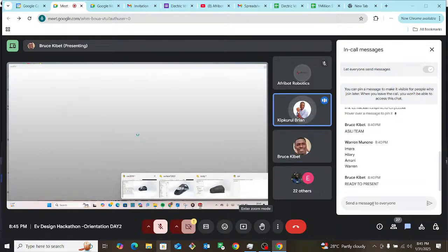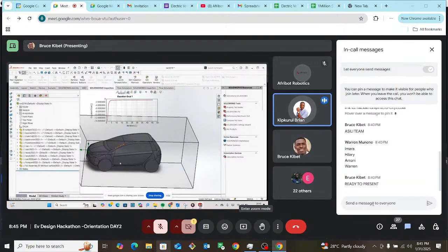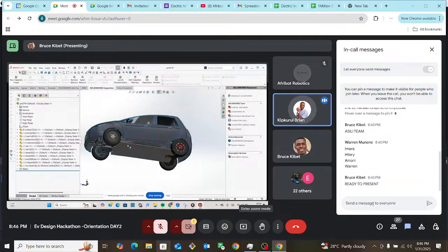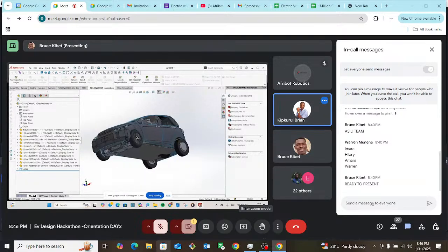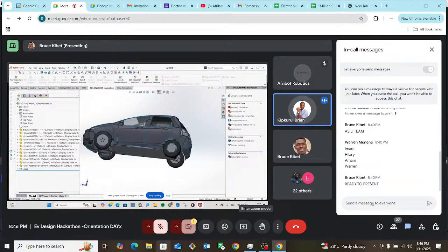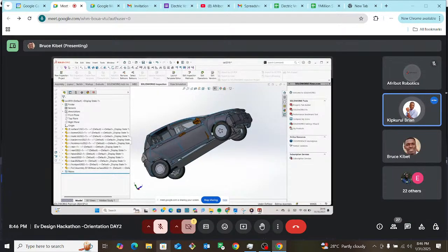Thank you. I'm going to be pretty brief on my part. I was using the same model design. We'll share the designs document with the email. I'm going to talk about the electric powertrain, specifically what drives the car. There are two hub motors on the front wheels, each rated at 12 kilowatts, and top speed is 120 kilometers per hour. They use two Fardriver controllers rated around 800 amps at continuous current discharge.